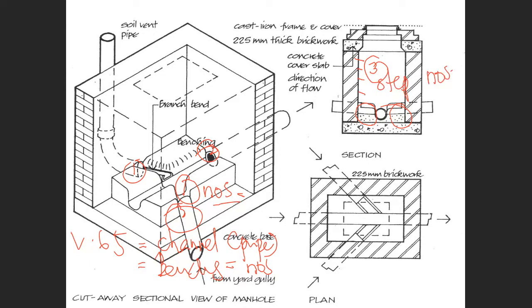Normally what you are given in the detail is the detail of center to center. Maybe they give you R16 dash maybe 250. So you should know that every 250 there is a step iron. Normally step iron is made from mild steel or high tensile bar. It is just simple bar reinforcement, not the reinforcement that you can see in your staircase measurement. Okay, and then another one, item number 4, you can see SMM uses the word cover. So the manhole cover also must be measured in number.